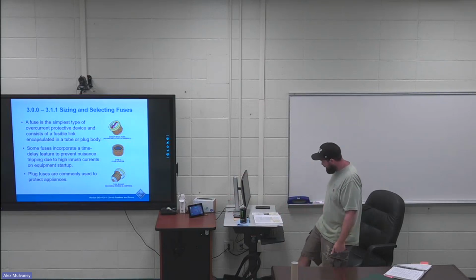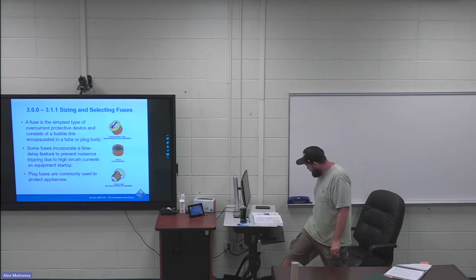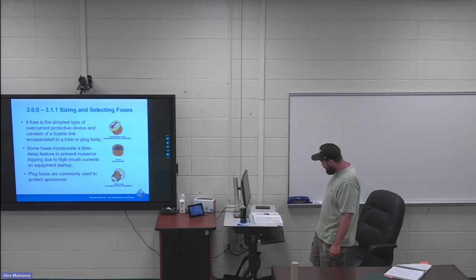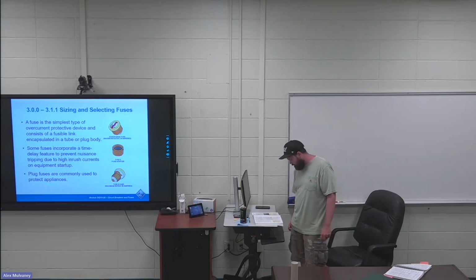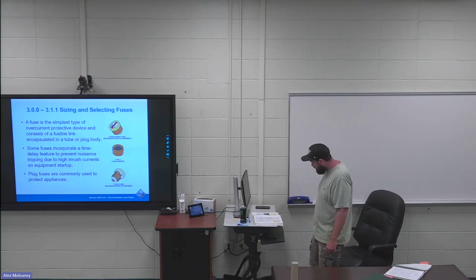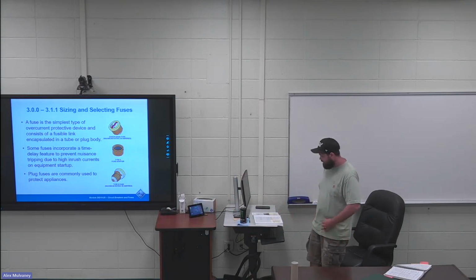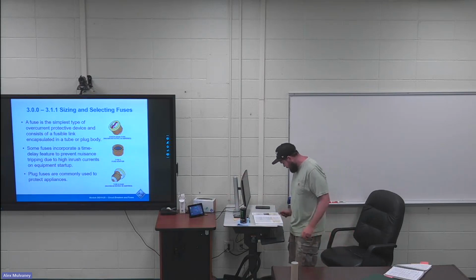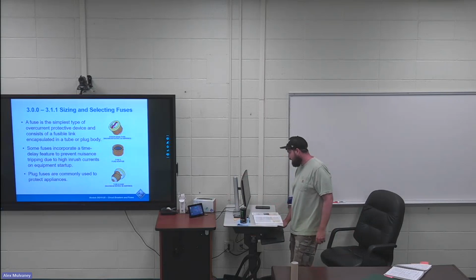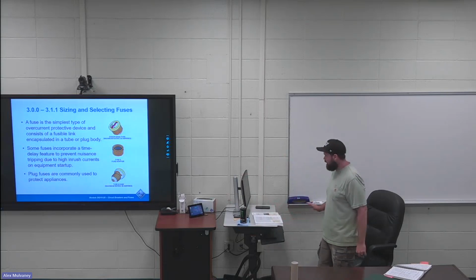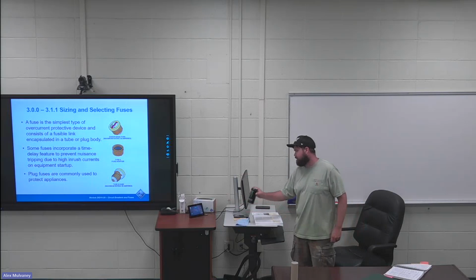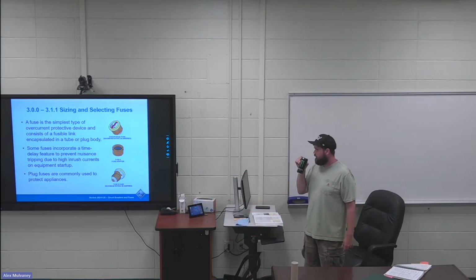Next paragraph, the whole thing's highlighted. Plug fuses are also made in time delay types that permit a longer period of overload flow before operation, such as a motor inrush current and other higher than normal currents. They are available in ratings up to 30 amps in both Edison-based and type S. Not used that much. I've seen them a little bit, but I would guess in the next 20-ish years those are going to go; there's not going to be a whole lot of those left.